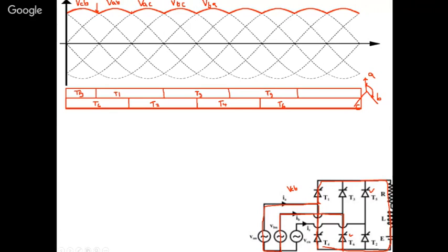This point, the red one which you can see here. I can just draw it in blue and show you. So this is the VCB. Until 60 degrees, this VCB is on. After that, T1 and T6 are on. So what is T1? This is A, and T6 is this arm that is connected to B. So the voltage you have to see is VAB. T1 is A, and T6 is B. So you want VAB, the next voltage. From this point to this point, you can just track this. This is your VAB.